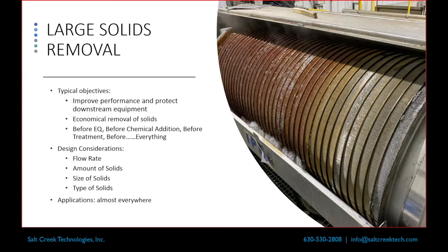The other important things are the amount of solids, the size of solids, and the type of solids. If it's a really sticky solid, it's not going to convey well in the screen. If it's a solid that has weird angles or is stringy, it can get through the wedge wire and hang up, and then you're stuck with it in the system. So that's an important thing too, and it's a pretty easy test to see how that is going to work. You just get a piece of wedge wire, run it over, and see how the solids come out.